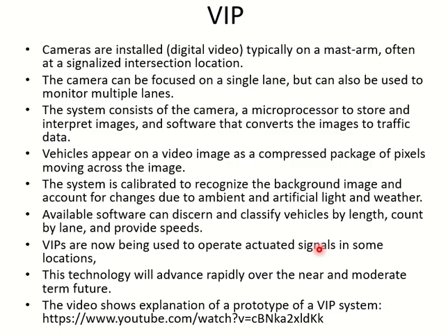So you need to calibrate the camera for different lighting conditions as well. You need to calibrate the software for different lighting conditions as well. Okay, so the black at night and the black in the day, they are not the same for the image, for the video. Okay, so the main item here is you need to take a lot of care in calibrating the software with this system. Once you have done the calibration properly, it can give you a lot of data, and it can help you even control the whole traffic system as well, because you have the full picture now.